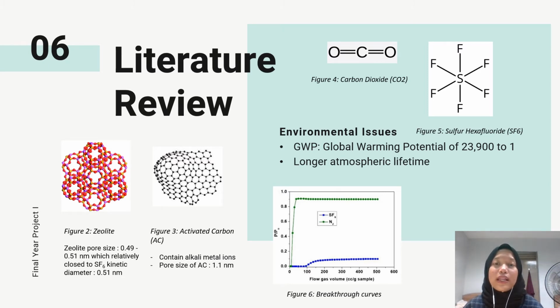Alright, so due to the less research on SF6 adsorption, that is why we are simulating the breakthrough curves to study the adsorption of SF6. From these curves, we can get the selectivity and also the gas adsorption capacity. As we all know, the gas adsorption capacity is much lower than the isotherm, because the adsorption capacity measured during breakthrough curves typically demonstrates lower capacity compared to the equilibrium condition.